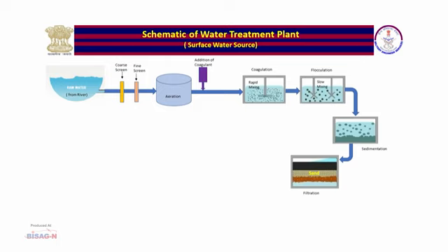However, for utmost safety of water for drinking purpose, disinfection of water has to be done for killing of disease producing organisms, etc. Modern disinfection process includes use of physical methods such as thermal treatment and ultrasonic waves, chemicals such as chlorine and its compounds, bromine, iodine, ozone, etc. and thirdly, radiation. Most commonly used disinfectant in water treatment plants is chlorine and process is called chlorination.